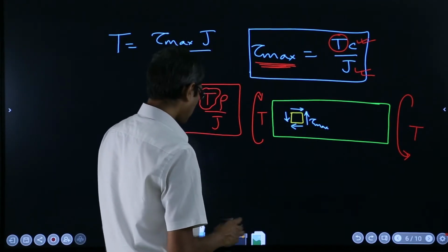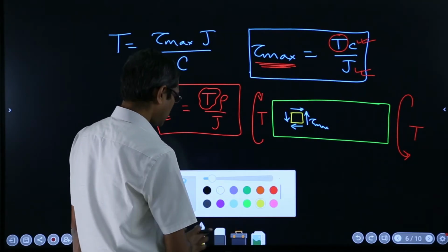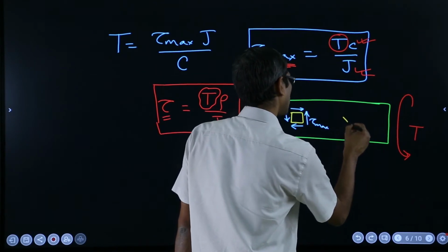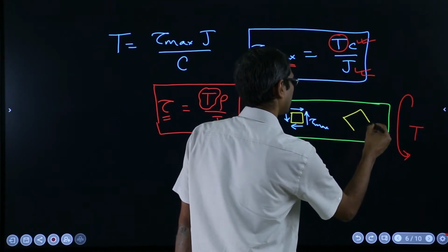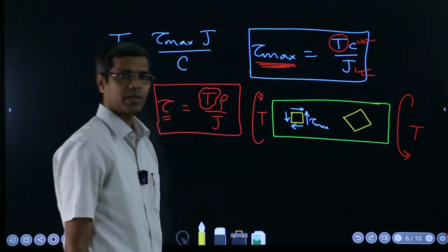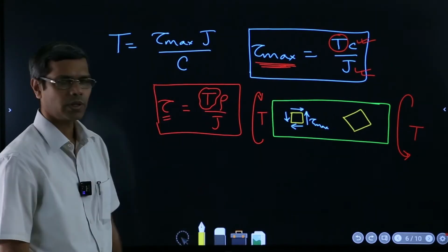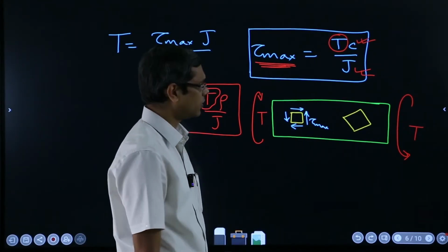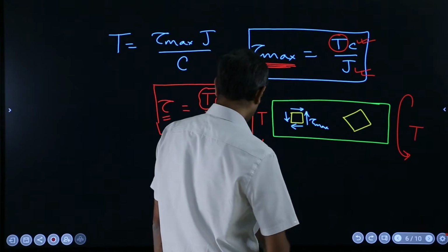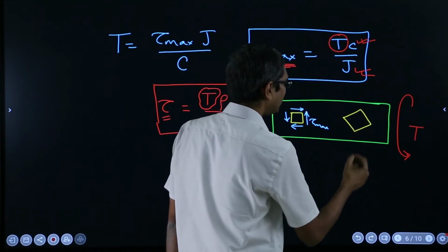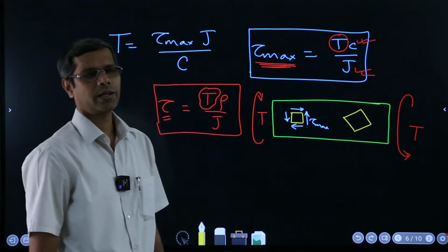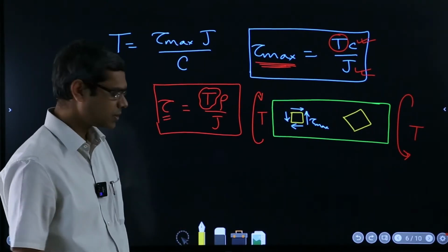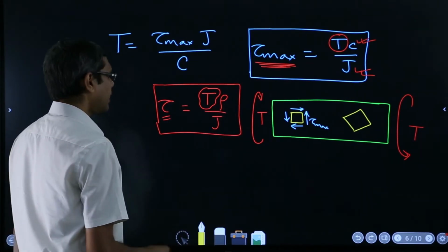But now we have discussed under our stress transformation that if now I take an element which is at 45-degree angle with respect to this original orientation, then what will happen is I will reach a stage where I will have only normal stresses, because that is the direction of the principal planes.